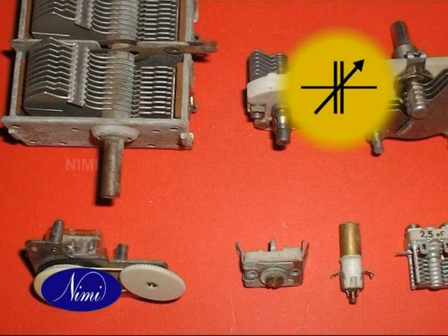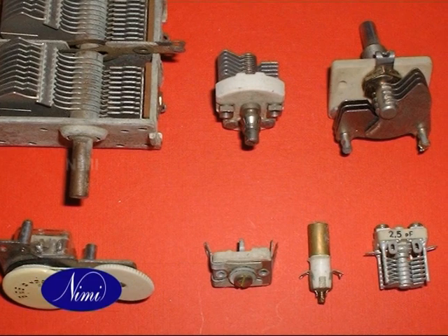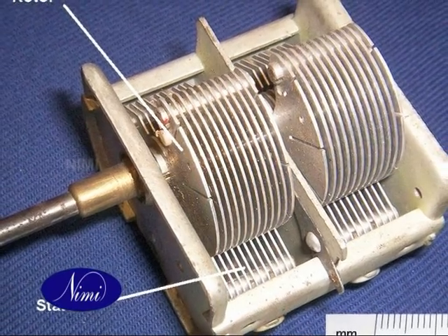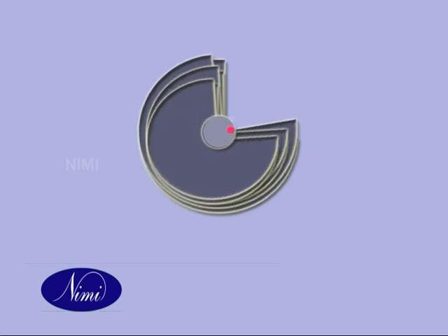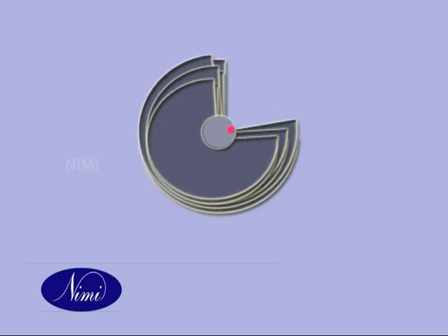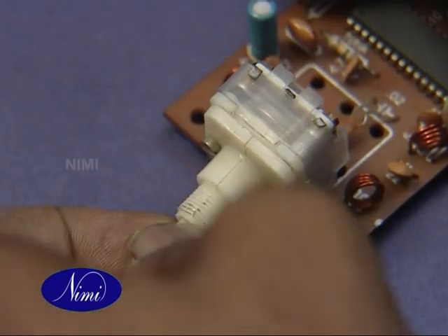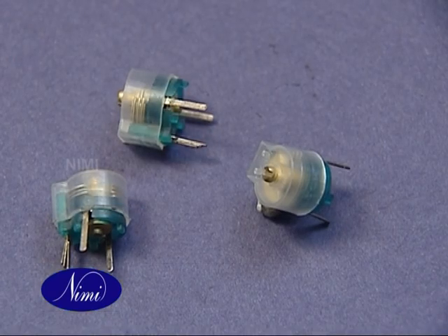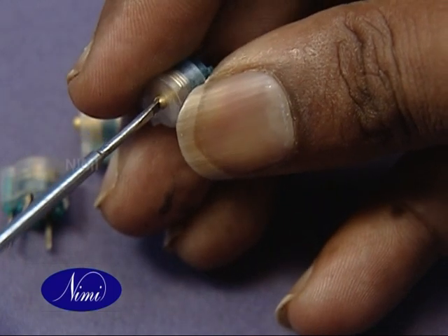Variable capacitors are used in a circuit when there is a need to adjust the capacitance value either manually or automatically. The capacitor is constructed with several plates that mesh together. One set of plates can be moved relative to the other, thus changing the effective plate area and the capacitance. The movable plates are linked together mechanically so that they move when a shaft is rotated. Trimmers and padders are adjustable capacitors. They have screwdriver adjustments and are used for very fine adjustment in a circuit.